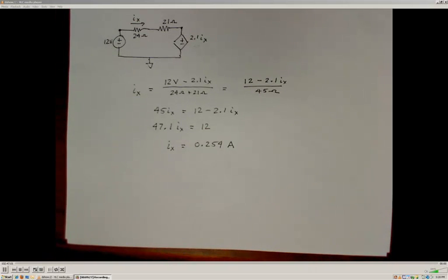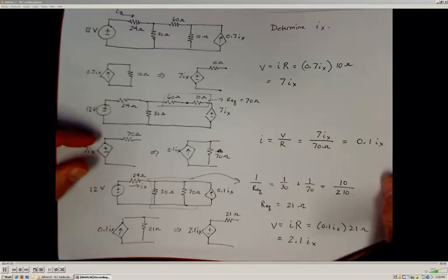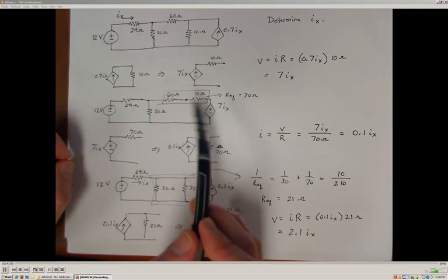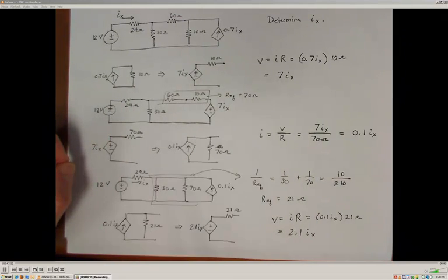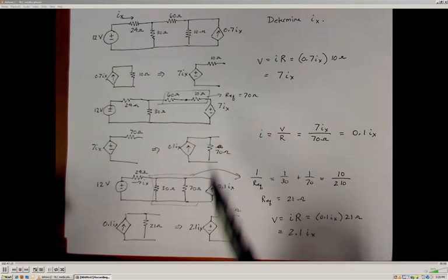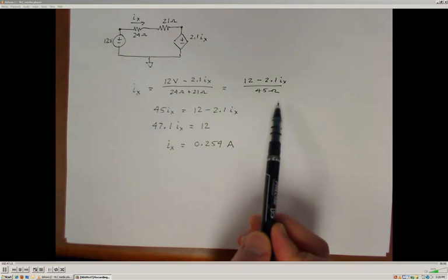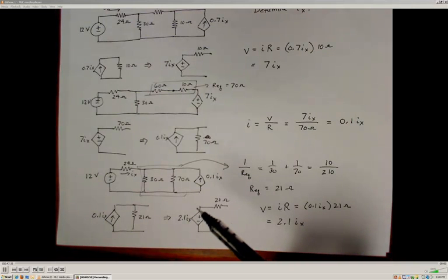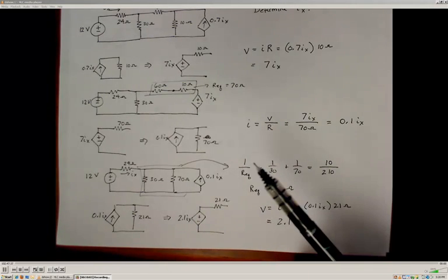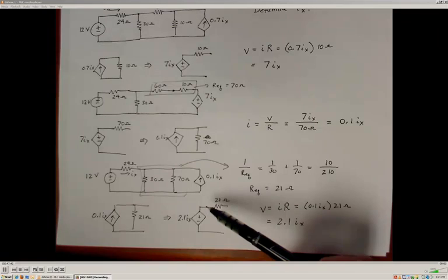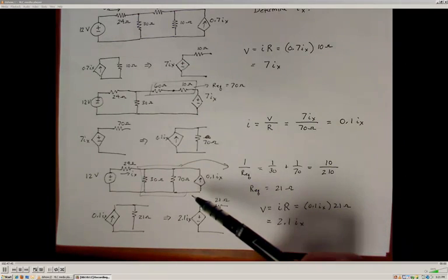Okay, so again, as a review, what we're doing is taking our Thevenin and Norton equivalent circuits and transforming between those two representations for the same type of circuit to simplify the circuit as much as possible, so that we wind up with a fairly straightforward and simple calculation at the end. Now, again, you can use the other methods discussed in the course: equivalent resistances, or the node voltage or mesh current method. So at any stage, when you feel like you've simplified the circuit enough, you can go ahead and then apply the node voltage or mesh current method.